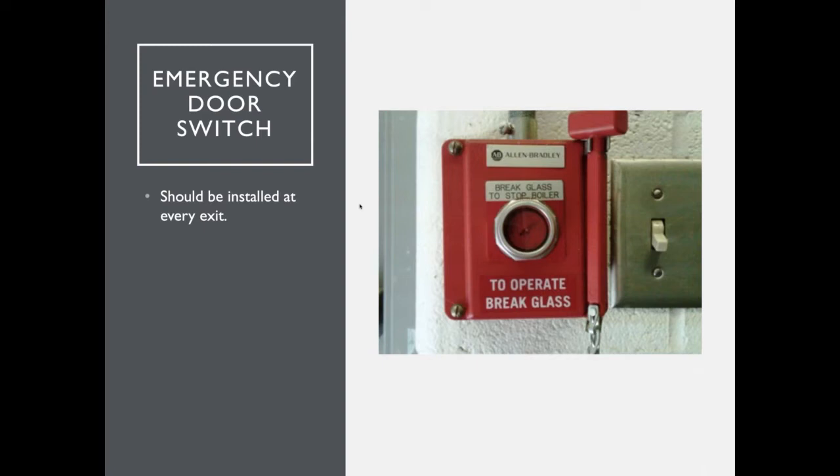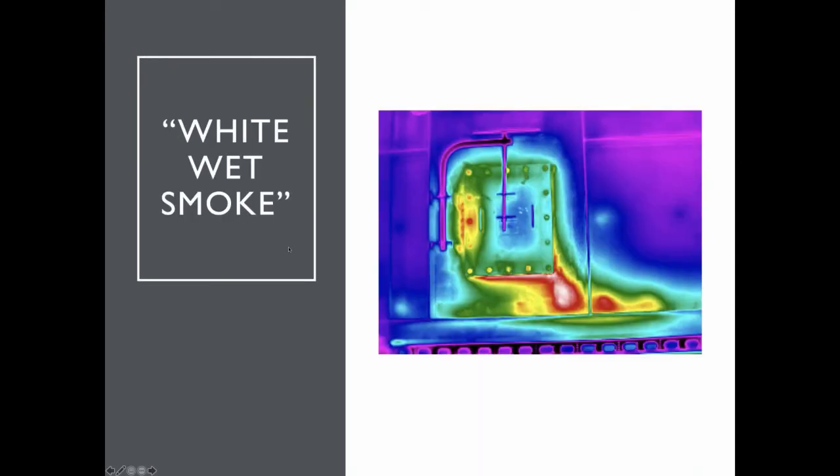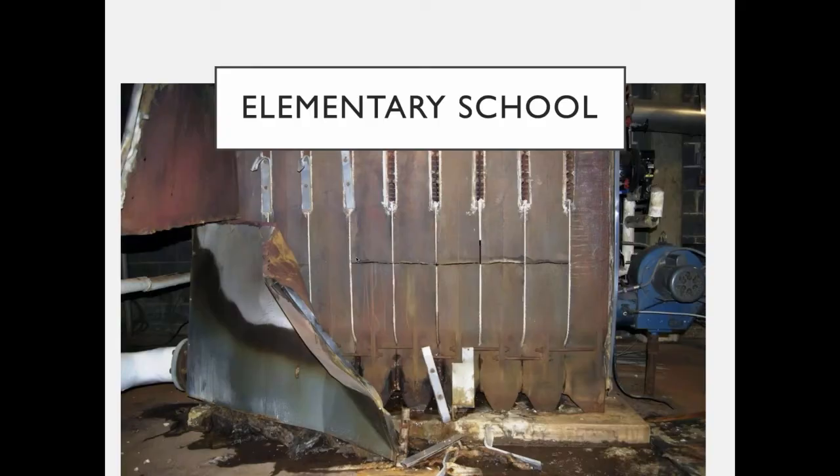This was a school district, and they got a call in the middle of the night, and their smoke alarm in the boiler room was going on. And when the fire department got there, they opened the door to the boiler room, and they said they were greeted with white, wet smoke, which is steam. So they said, well, we need to find the source of this white, wet smoke. So they went down with their thermal scanner, and they said, there it is. That's the source right there. And they took a picture of the boiler. And then the next thing they did shocked me. They sprayed the boiler with cold water while it was firing.